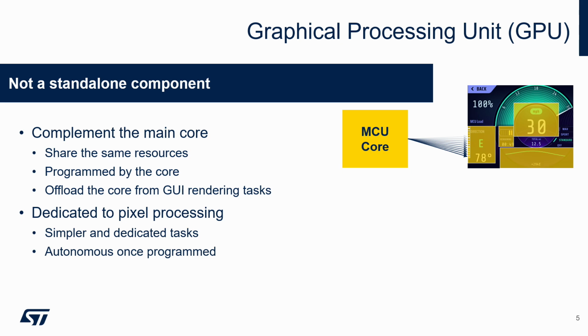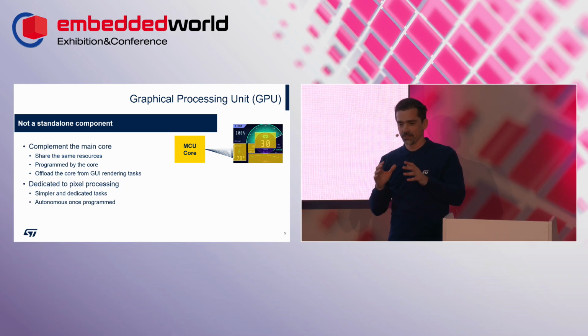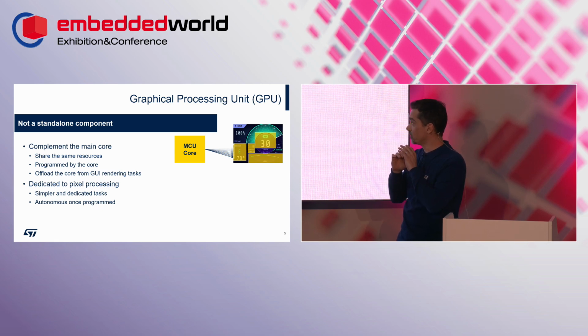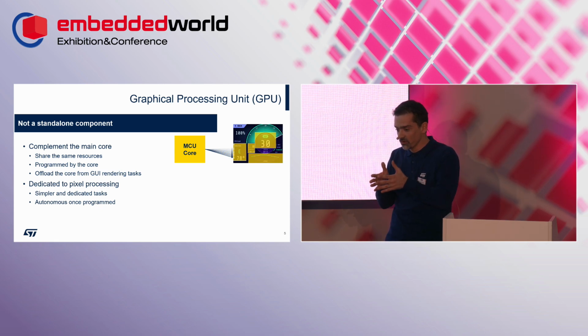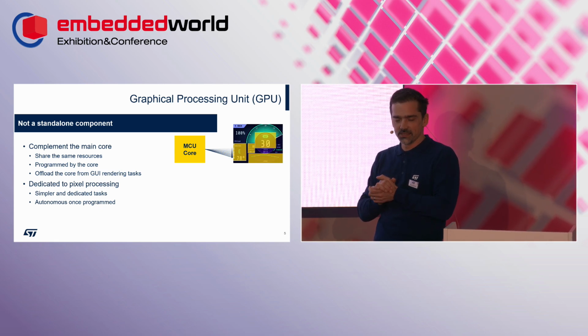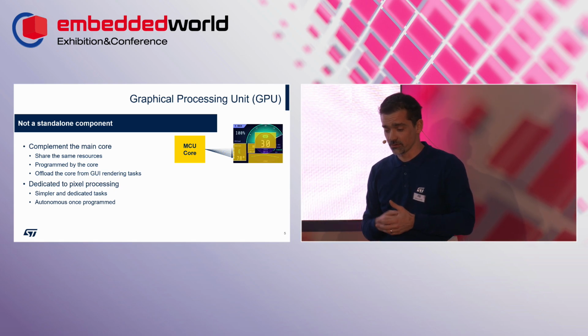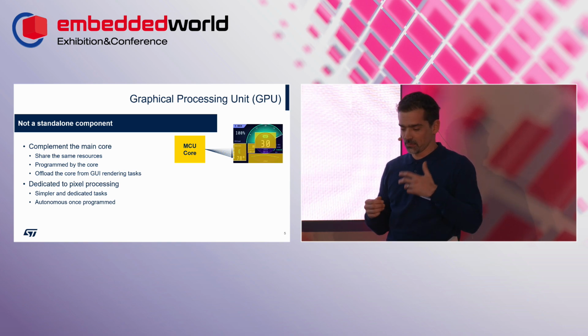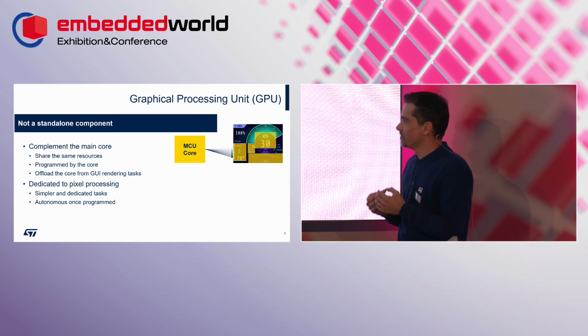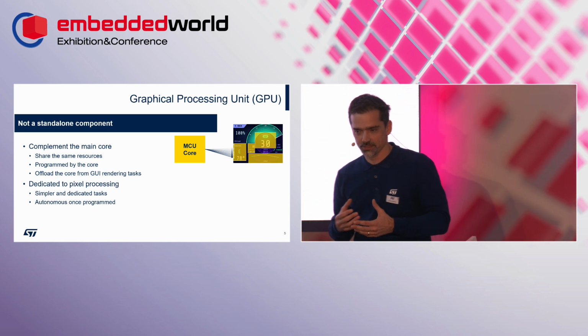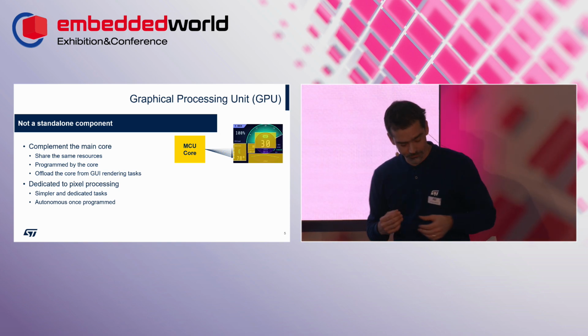So when it's doing this, if you want many things to update on the user interface, the Cortex will be stuck and will do almost only that. This is not what you want: the Cortex must address other points, like getting a temperature sensor reading, programming an ADC, and all. The Cortex is there to drive your product. It's not there to only update the user interface.